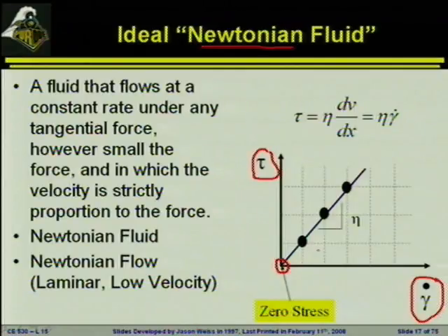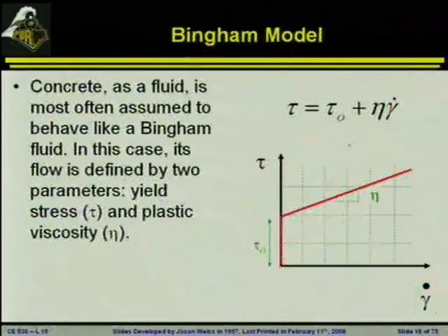So the basic idea is we end up with a very simple equation. This is what we were talking about up to this point, where the shear stress is related to the strain rate through the material property that we call viscosity. Now it turns out that this is a fantastic equation for materials like water, but unfortunately concrete isn't always like water. Concrete doesn't necessarily behave like water, and probably the simplest way that we could assume that concrete behaves is something referred to as a Bingham model.